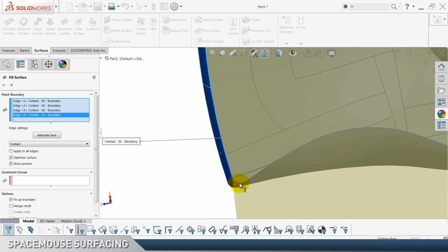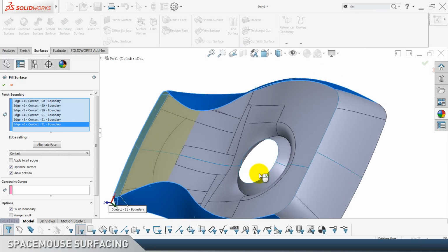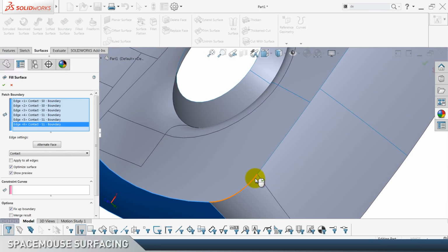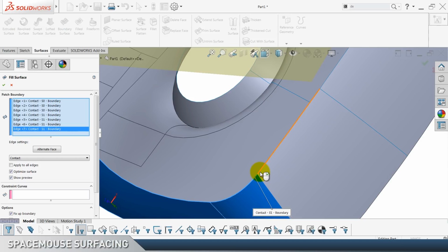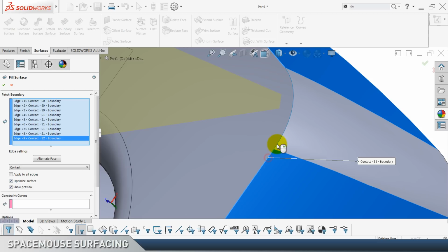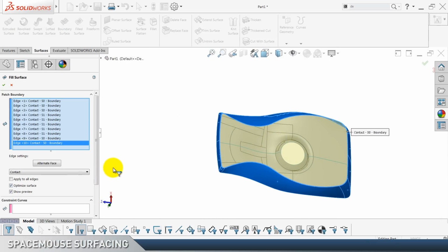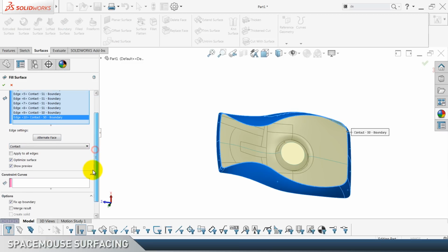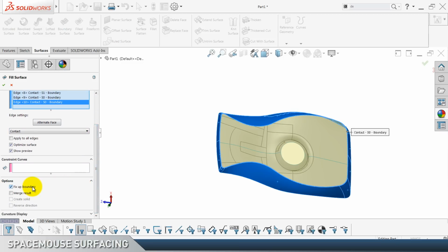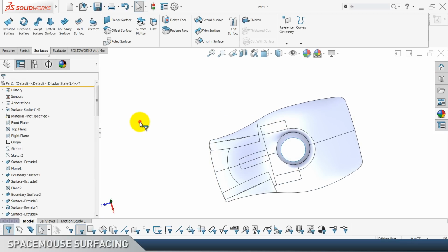Basically just select all these bottom edges of these surfaces or faces, however you call it. As you can see, it works fine, and it has to be just contact. We want flat face, and we select merge result. It's gonna do the same thing like we pressed knit.